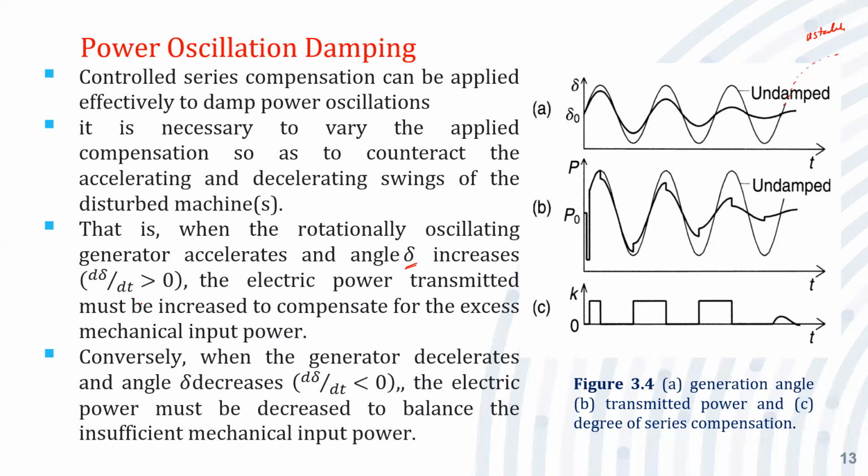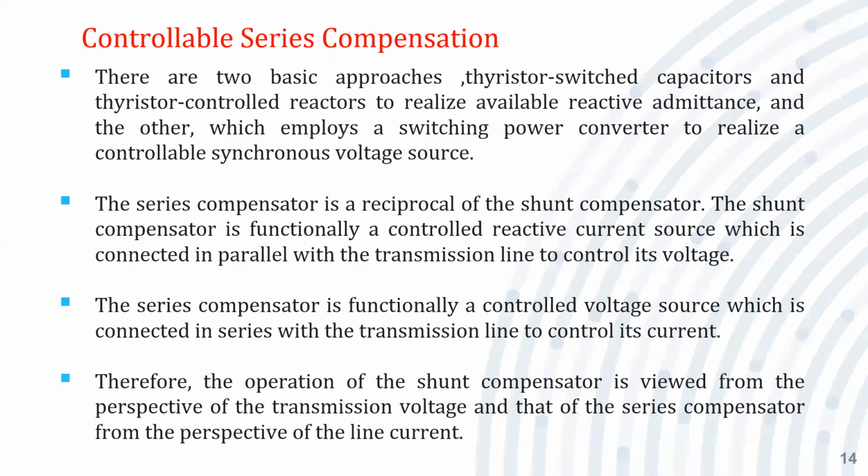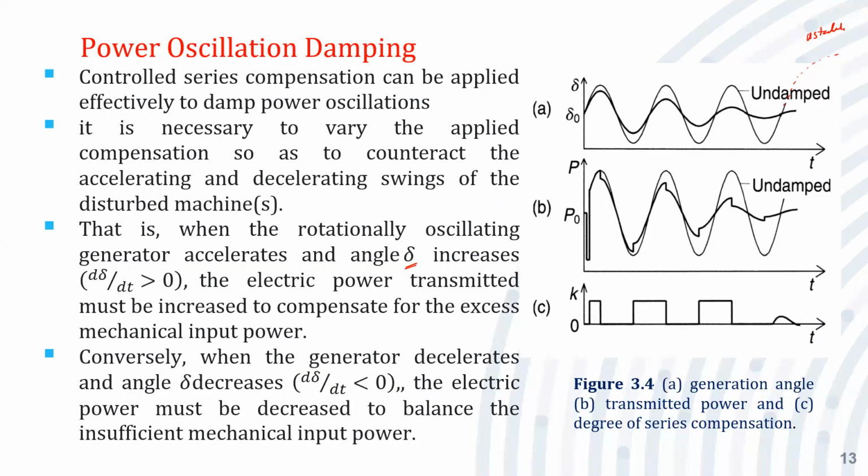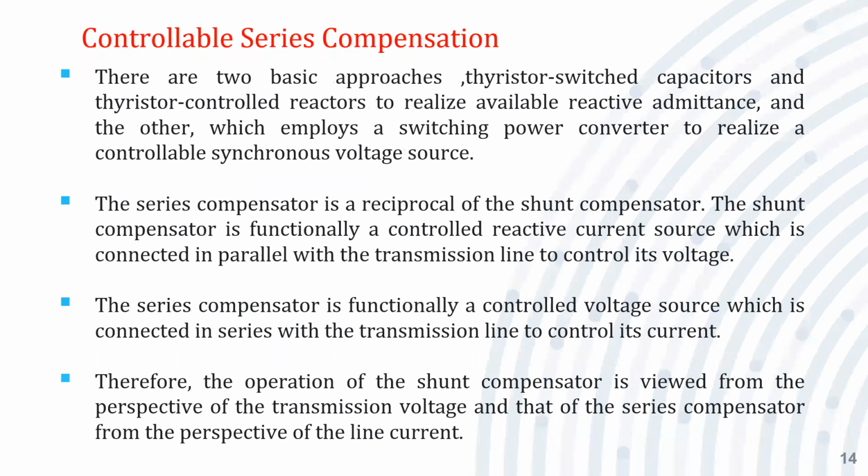So these are some applications of the series compensation. Very first, it improves the power handling capacity. This first point is very important: to increase the power handling capacity. Second, voltage stability. Third, transient stability, and damping out the oscillations in the angle as well as power.